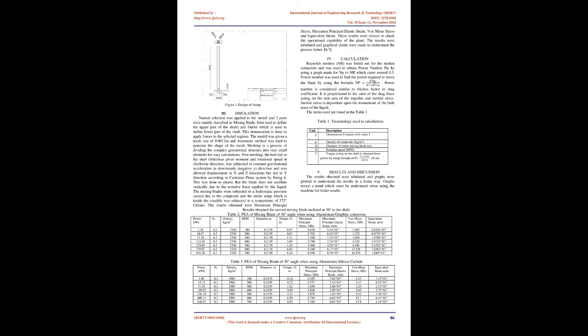The mixing blades are made of stainless steel 304, which has an ultimate tensile strength of 586 MPa. Stainless steel is used because it ensures that the mixing blade does not corrode due to high temperature conditions. It turns at high speed on a shaft mounted centrally in the vessel. Principal currents are generated in the liquid due to mixing, and this causes high turbulence to be developed in the area surrounding the mixing blade. The mixing blade has been positioned in a way that vortex formation is less in order to ensure proper mixing.